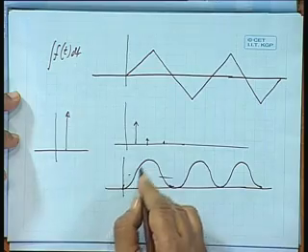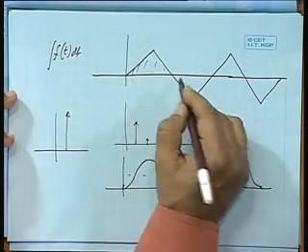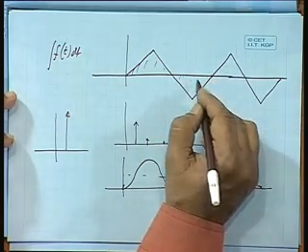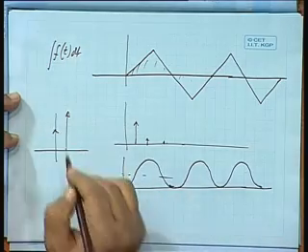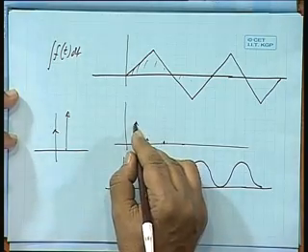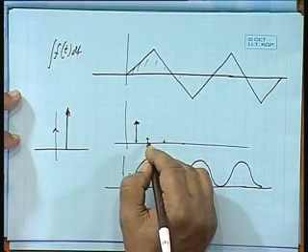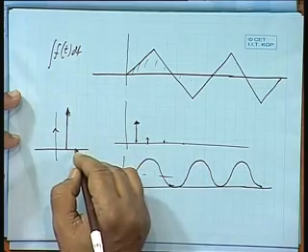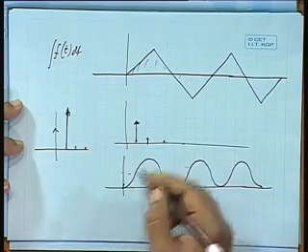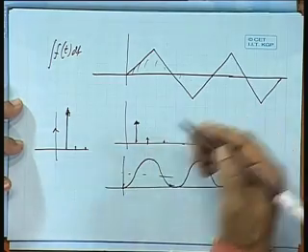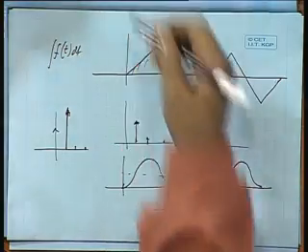So, a smooth function means it contains less of harmonics. So, the fundamental will be very high. It may have a DC value also, because now it is integrating, and integrating this, you get positive area, and then that starts reducing, it becomes 0 here, it never becomes negative. So, it is always having some average value. So, it will have this, and then this is further increased compared to this, their relative magnitudes will be much smaller.